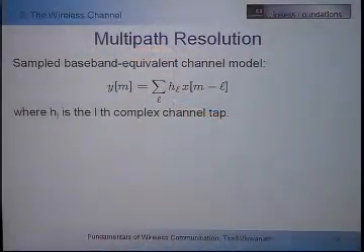So this says that the received symbol at time m is a sum of the previous symbols transmitted, multiplied by a certain gain depending on the delay, h sub l. Okay? So this is my discrete time channel, and this is the channel that I'm going to see. The fact that you have multipath is reflected in the fact that the system has memory. That is, the previous symbol may affect what you see currently because those paths take some time to get here.